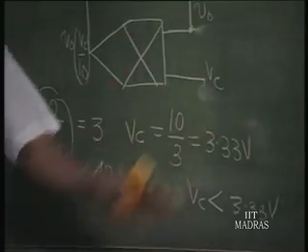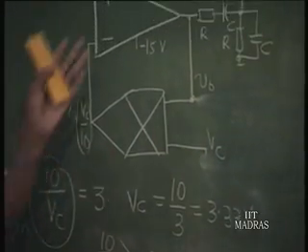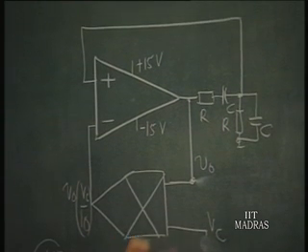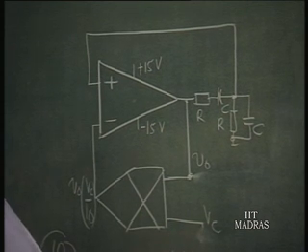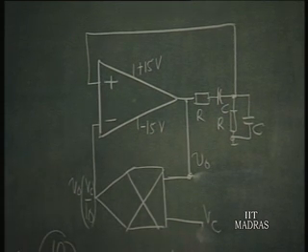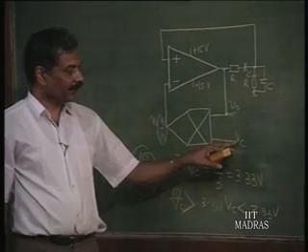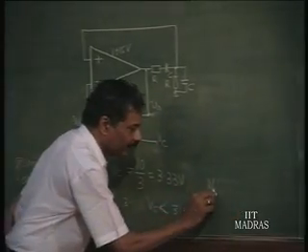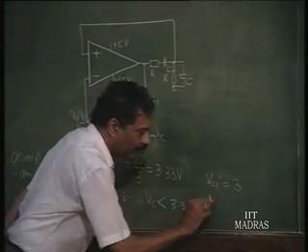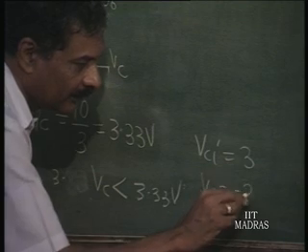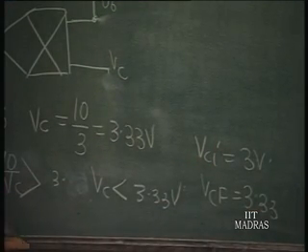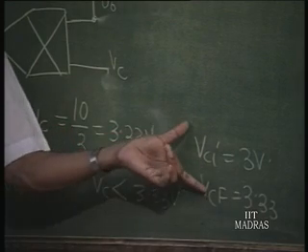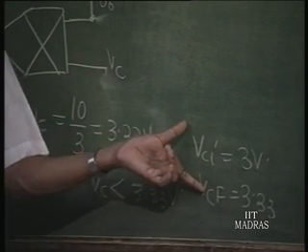We can now put our AGC, AVC system here such that to start with this voltage is somewhere around 3 or so, and then it goes on to 3.33. So, we can have an arrangement where Vc starts with, let us say, Vc initial is 3 and Vc final is 3.33. So, we must have an arrangement like that. This is necessary for us to start the oscillation.